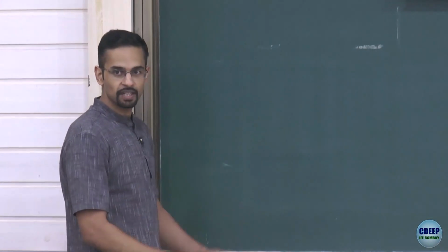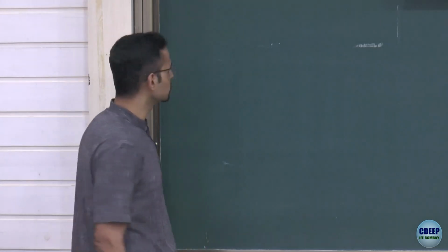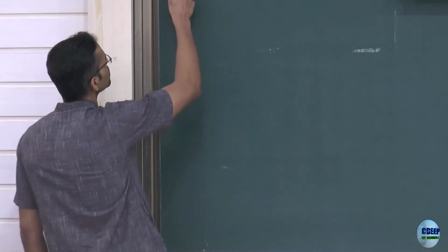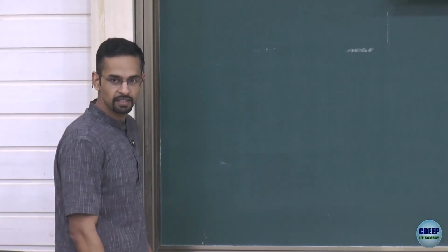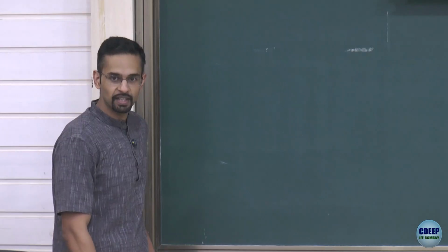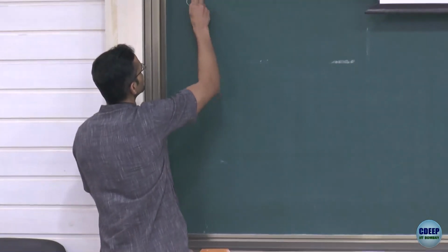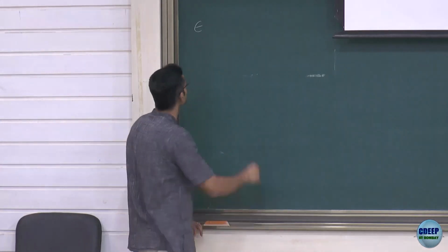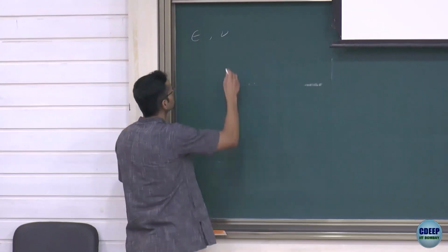So just by way of recap, what we saw is if we're looking at homogeneous isotropic turbulence, right, far away from walls, with no strong mean shear or mean flow. So in such a situation, if you're forcing the flow at some large scale L, and you are inputting energy at a fixed rate, the flow reaches a stationary state. And what you want to know is what is the nature of the range of scales, how does the velocity field scale, etc. So we said we are inputting energy at some rate epsilon. This is the rate of energy input per unit mass, per unit time, in a fluid of kinematic viscosity nu. Okay, so those were the inputs.